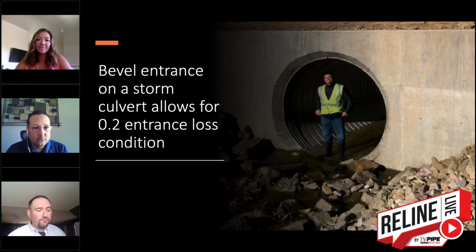Now, I'll tell you, I just came from looking at 4 pipes in Southern Connecticut yesterday, where every single pipe, the bottom was rotted out. It's nice, beautiful old New England stone-built head walls, but the bottoms are rotten. The head wall is blown apart at the bottom, and there's a scour hole the size of Texas at the outlet.